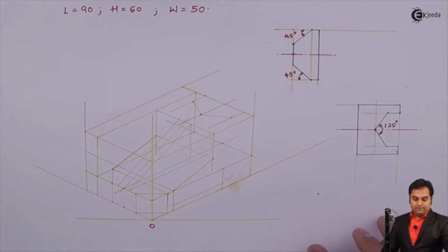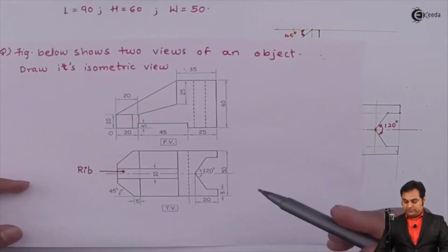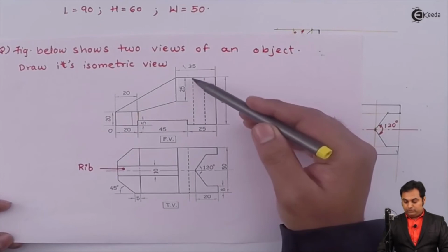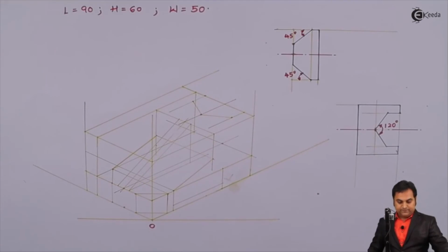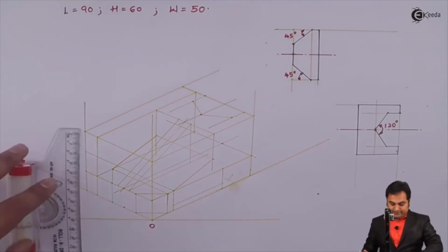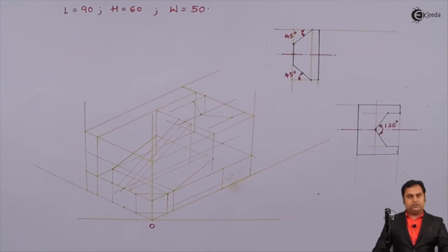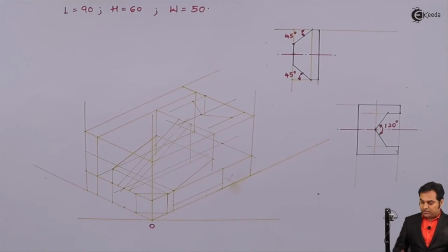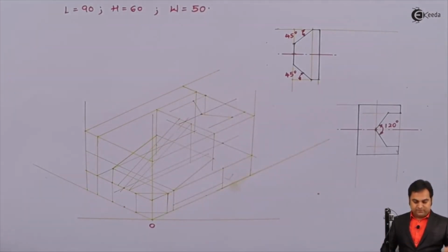Then after I had drawn this surface, now in the front view here there is the hidden line, and both these hidden lines show this surface that it is throughout. For that, I'll have to draw a light vertical line. So once I have reached up till this level, now I can start making this drawing dark step by step so that we can understand what is given here. Starting from the same surface which I have drawn first, so I'll make it dark.